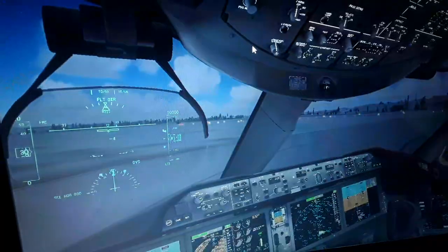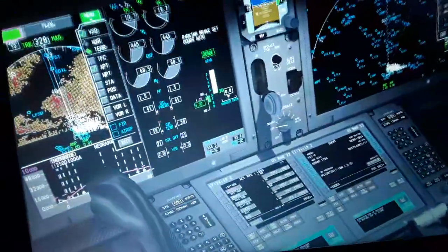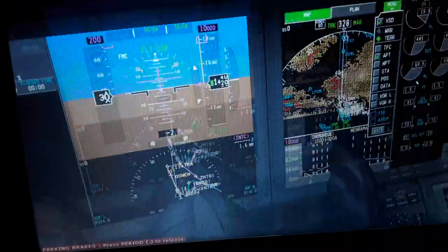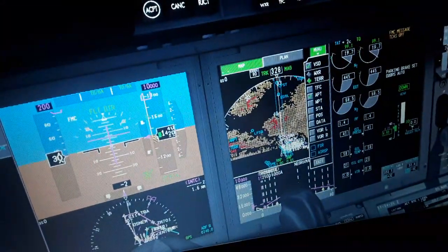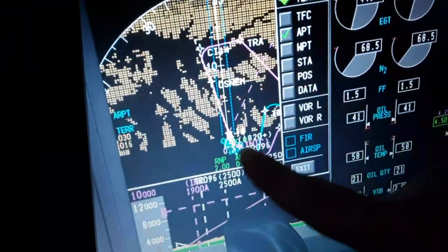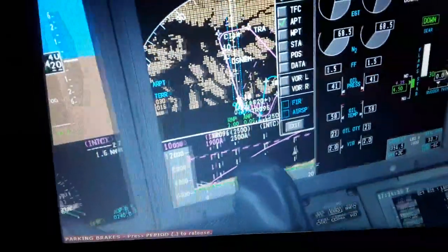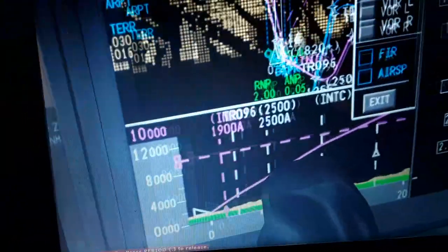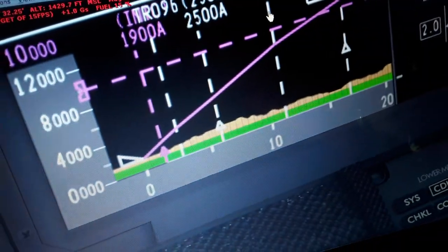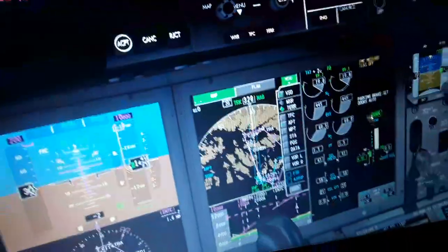in the virtual cockpit. We need to set the flight management computer now. We just did that. We can see a little bit more of the displays again. So I talked to you about the primary flight display. Now you can see the flight plan here created. Also the terrain you can see. We look closer. The flight plan is going to be shown with a purple line we need to follow from takeoff, climb, cruise, descent, approach, and landing. The runway also position. In the vertical you can see the terrain and the cruise level we cannot change. Also the terrain below us and the line of climb over here.